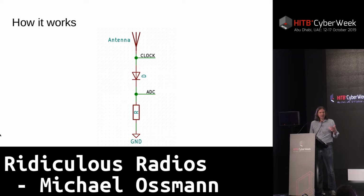So the microcontroller has a CPU in it. That's its main feature. And the CPU can be configured to run on a variety of different clock frequencies. It also has a couple of other parts inside that require clocks. For example, the USB controller requires a clock signal. So one of the features of this microcontroller is that it has two or three fairly flexible clock generators inside of it, and they can operate at frequencies up to a few hundred megahertz.